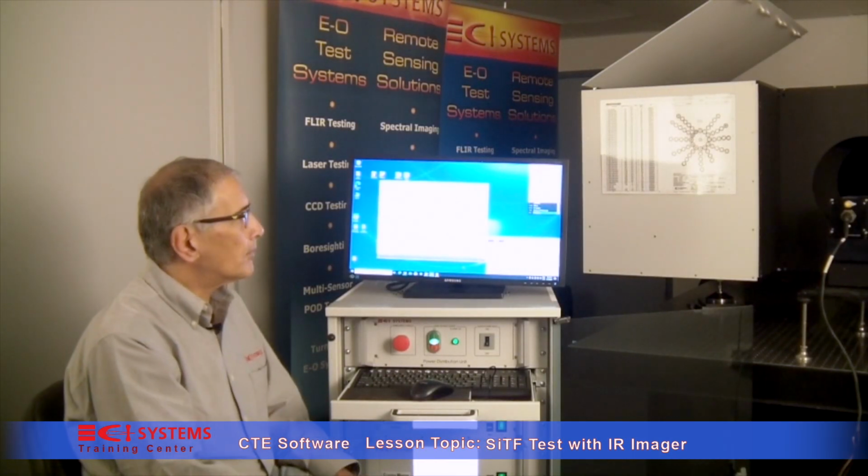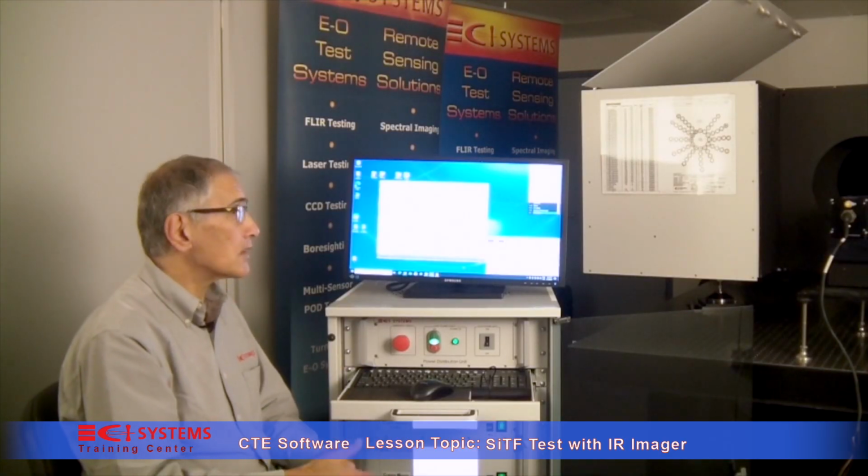Set up the SiTF test. SiTF is a signal transfer function for the thermal imager, and it will help us determine the saturation points of the camera versus the signal and temperature. We need this so we know where the linear range is that you're working with, as well as using this gain factor, or what we call the SiTF, to convert the analog to digital conversion of the frame grabber into something more meaningful, like temperature units.